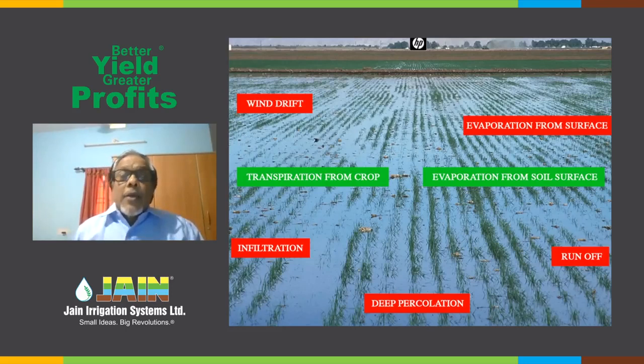So there is actually a give and take in this, and the give becomes more than the take. In other words, if you are flood irrigating, you are following a method of irrigation which is not sustainable, because every time you are exhausting a certain volume of irrigation water which you cannot recover.